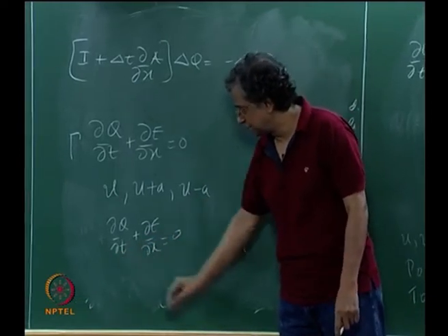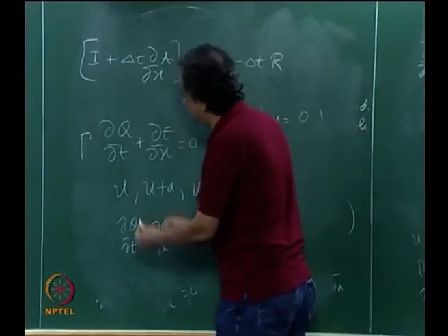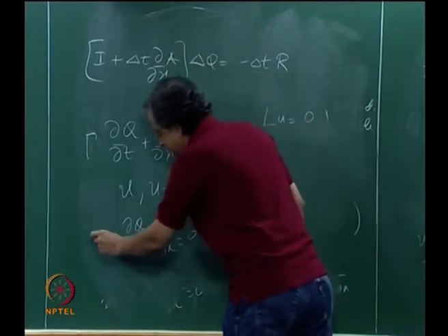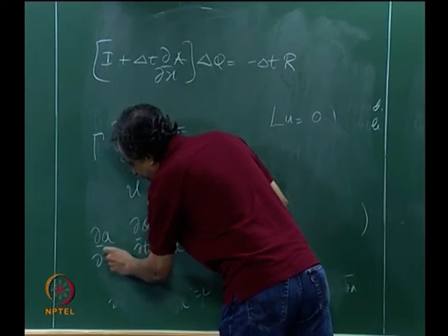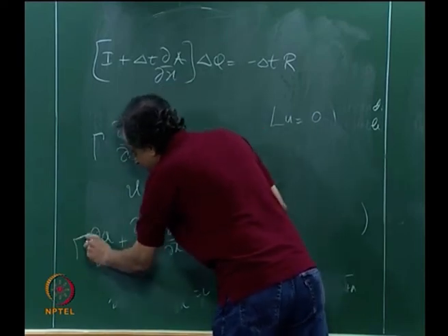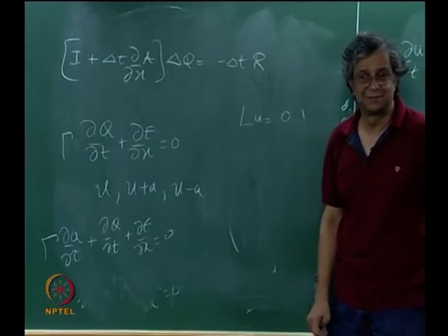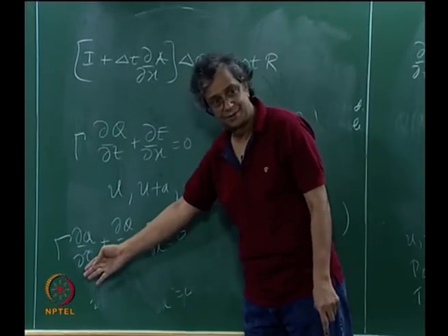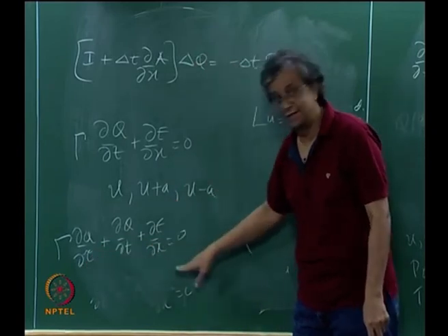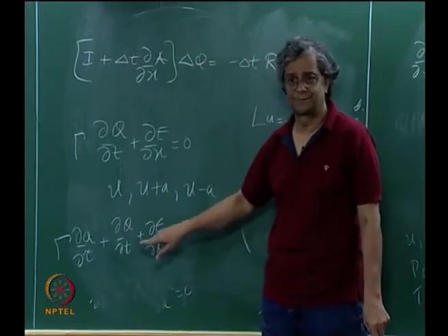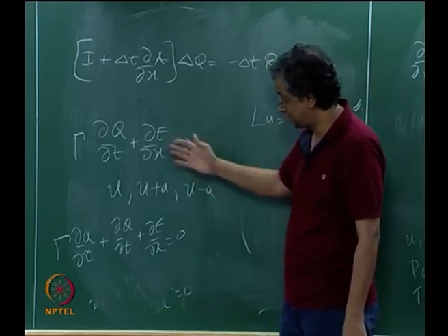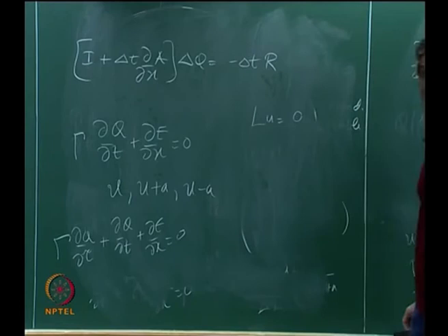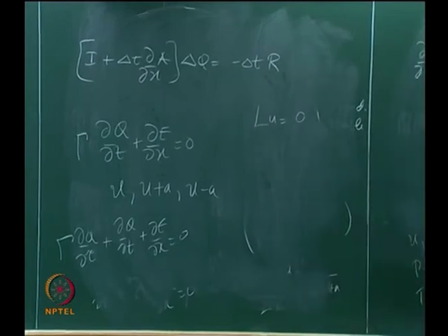You could use Runge-Kutta or whatever it is, but what we said is, oh, we have built up so much machinery for steady state solution that if you add a pseudo time term ∂q/∂tau, and then, because that is going to 0, multiply that by a preconditioning, you could actually converge to the steady state in tau and get the unsteady solution in real time that you want, okay. So we were then talking about acceleration schemes, right, and then we went back and basically remembered that high frequencies decay faster than low frequencies. We recollected all of these things.